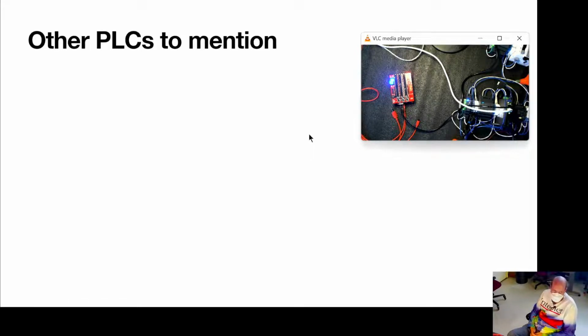So yeah, there's a bunch of features that are represented by the physical build of these devices that don't line up with the way that having an Arduino in your panel or a Raspberry Pi or whatever else does. For example, the Click, when we were connecting to it, it was telling me the project saved in the PLC. I can save the code in the PLC as well. So if I'm working on like plant automation stuff, I can save the code in the PLC in addition to my file server so that the next technician will definitely have my code. But if I'm shipping a product, I can turn that off, saving the code in the PLC, because I don't want the technician on the product site working on my screw compressor or whatever to connect and change the code inside of my screw compressor or my hydraulic press PLC or whatever.